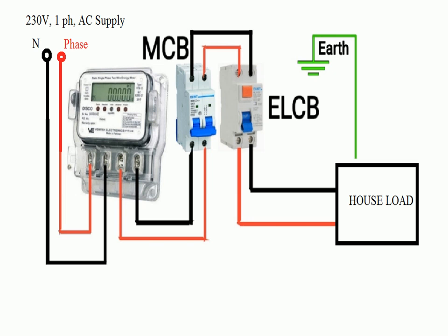Every advanced building has these two very important devices. ELCB, earth leakage circuit breaker. If any leakage happens, then this circuit breaker trips. This is also a double pole double throw switch, similar in structure to the MCB. Hence the MCB output is given as input to the ELCB breaker. Then the output of this ELCB is taken for further connections, that is, the different house connections.